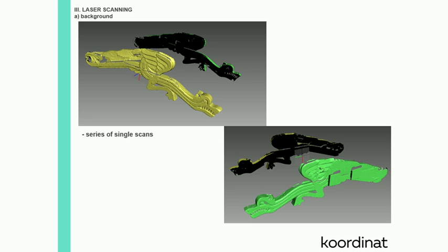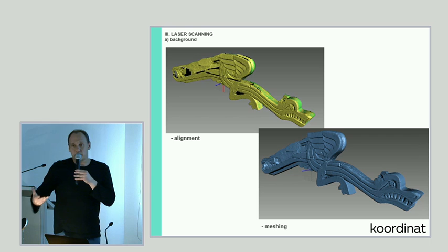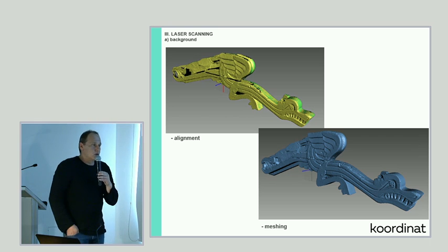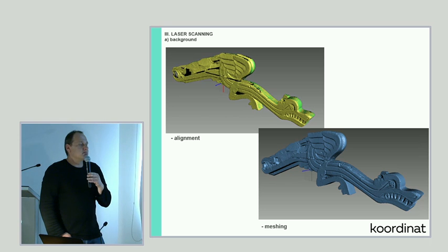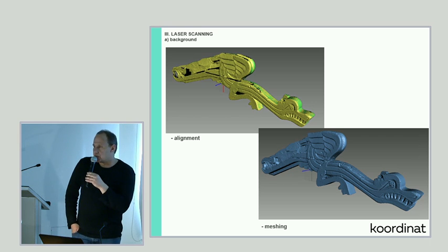This is an example from the Norwegian buildings taken out of the United States, actually. It's a wooden dragon from a building that was part of the World Exposition in 1896. It was taken home to Norway last year. So you make a series of scans, then orient them together and fuse them into a model. Normally, in everyday work, I use scanners from 0.1 to 0.5 millimeters when dealing with smaller items, and of course standard terrestrial ground scanners